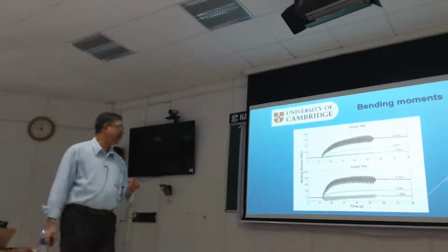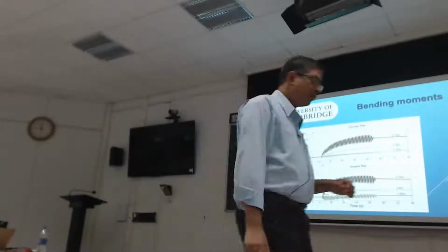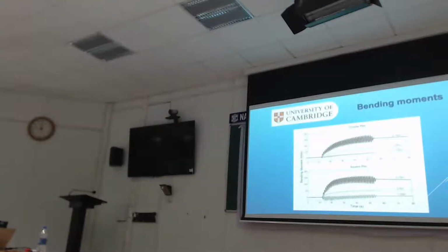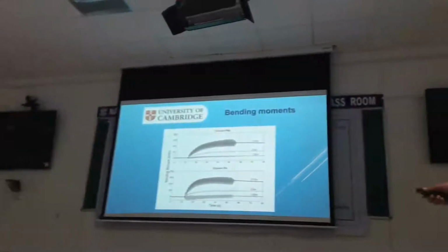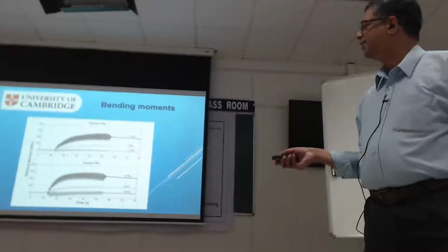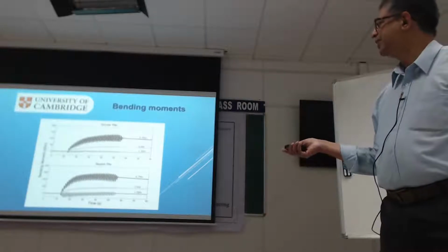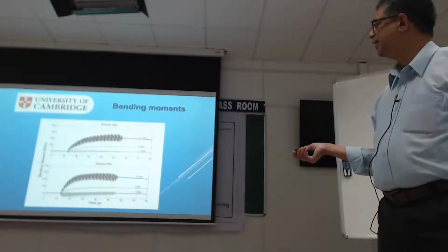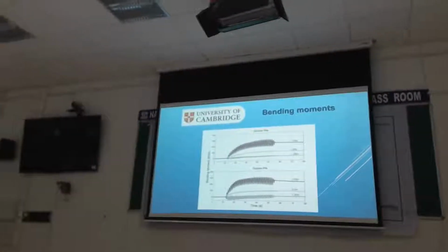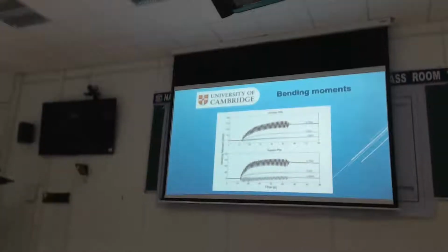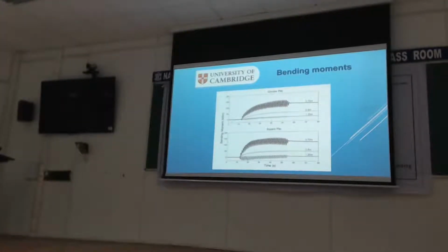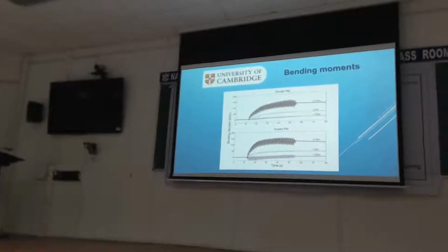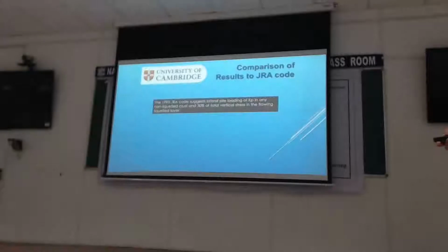So we looked at the bending moments in the circular and square piles at different depths. That's just the data showing. We got bending moment time traces at 3 locations, and they look different for circular and square piles. The square pile is picking up more quickly, while this is more gentle, and otherwise very similar. Boring. But that's not the purpose of measuring the bending moment.